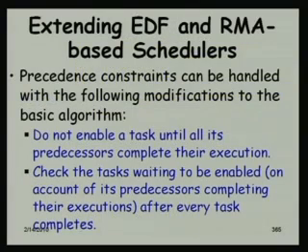Okay, now let us see. We saw that for cyclic schedulers, it is not very difficult to handle task dependencies. Simple algorithm, just find out their worst case completion times, and based on that we said what is the earliest, what is the latest by which it should start, and then for each of them we did that and moved them forward, right, simple thing. But now let us see how we extend the EDF and RMA to handle task dependencies.